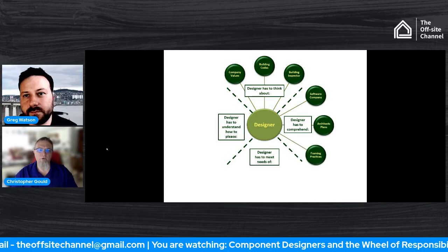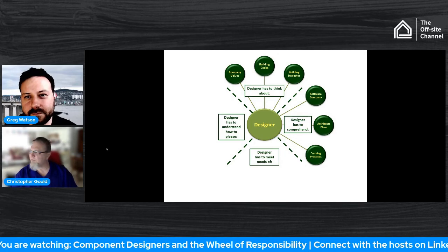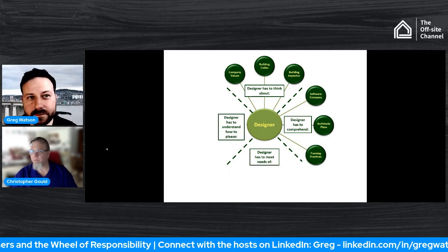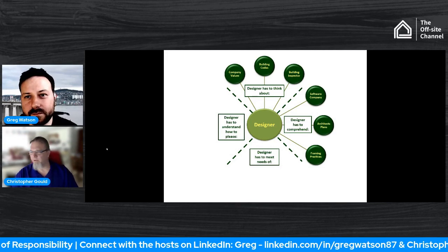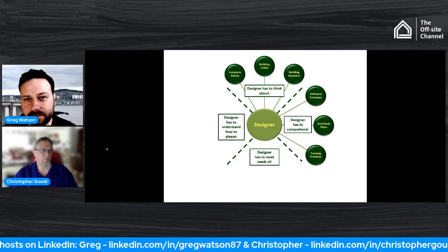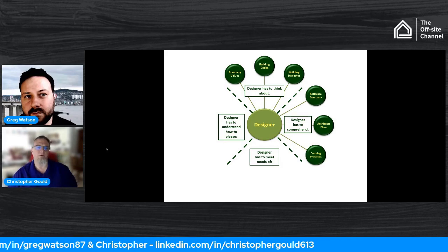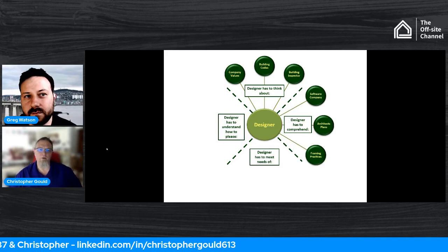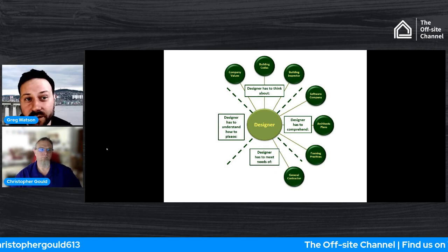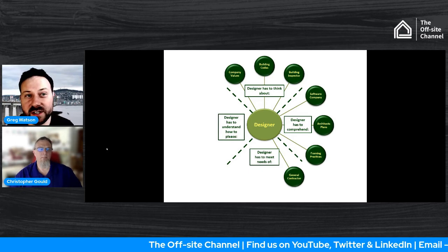And we also have to understand and comprehend the framing practices. Different regions have different practices. Maybe different customers have different practices. For example, some guys don't want valleys. Other companies got to have valleys. You know, those little subtle nuances that could make your price too high or too low. Yeah, and that could be state to state, region to region, country to country, couldn't it? I mean, you've got to be knowledgeable. Right. Different building codes within those regions and countries as well.